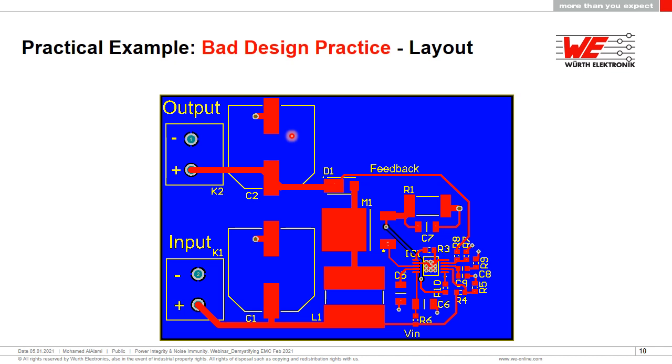So those are the two main aspects when it comes to improving a design: component selection, where we're looking for more optimal components to reduce the noise, and much improved layout and tracking. Between those two, you can get rid of quite a large volume of your EMI problems.